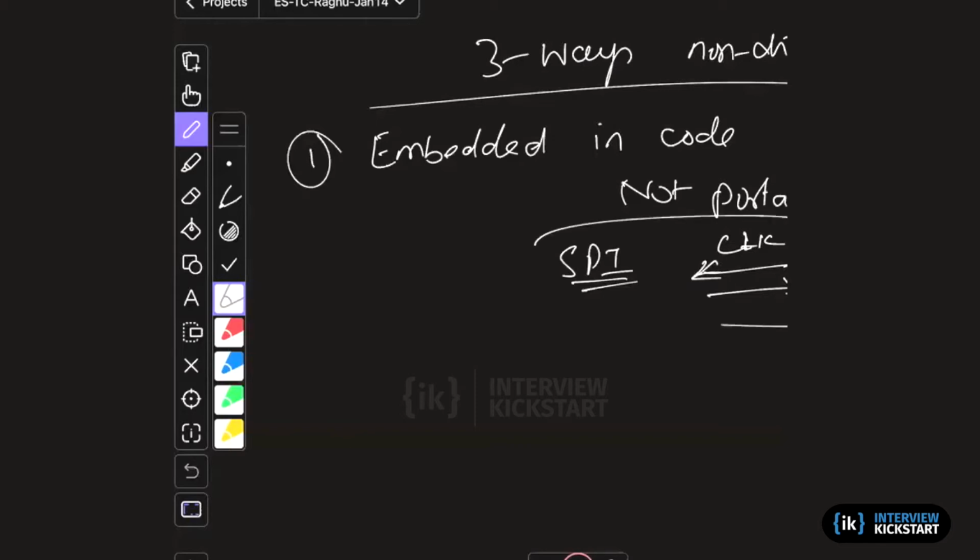But apart from this serial, there are non-standard interfaces. For example, what IRQ it will be using, and how do you do slave select? If you have multiple slaves on the SPI bus, the slave select is normally done by a GPIO line, right? So you would actually use a GP output line to address. These are outside this definition of the SPI. It is specific to a hardware platform. So you need to capture this for the driver to be able to correctly operate on a given platform.